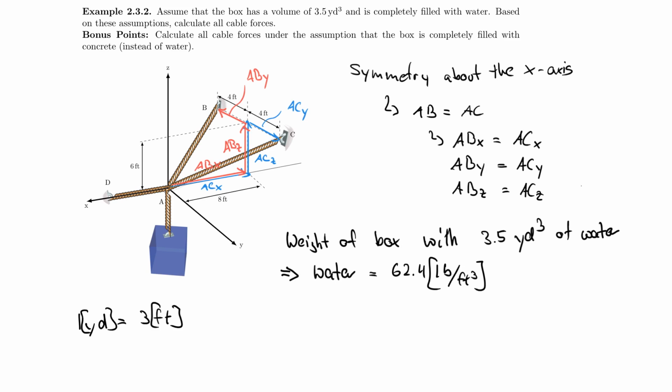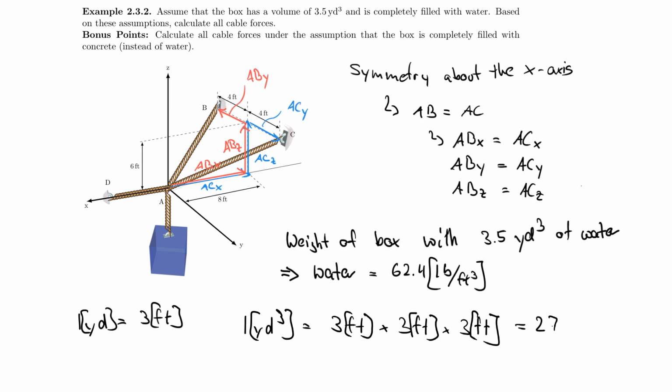And then sometimes they think, okay, I'm not going to fall into that trap, so I have to obviously multiply that by 3. For whatever reason, I don't understand, because they understand that we're not dealing with linear dimensions here, but we're also not dealing with square dimension with an area. We're dealing with a volume. So in reality, 1 cubic yard is actually equal to 3 foot times 3 foot times 3 foot. And so the answer is not 9 cubic foot, which is an answer I often get in the classroom. It is actually 27 foot cubed.